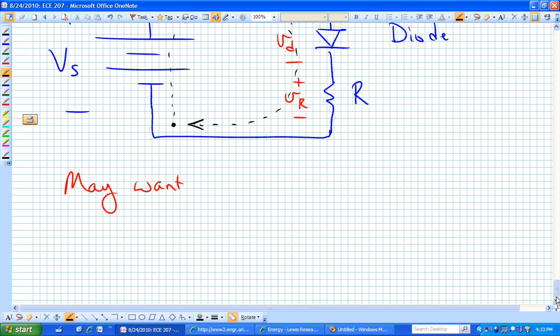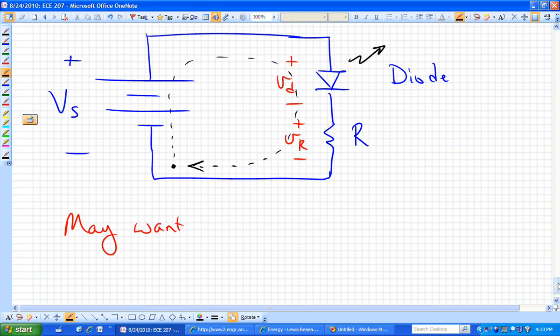you would say, the voltage goes up, actually just goes straight up. So let's say this was V sub S, that's now the height. Then you have some drop across that diode, and then some more drop across that resistor, and you get back to where you started. And all we've shown right now is the battery potential, how much voltage there is across those terminals, and then you drop that voltage down, some across the diode and some across the resistor.